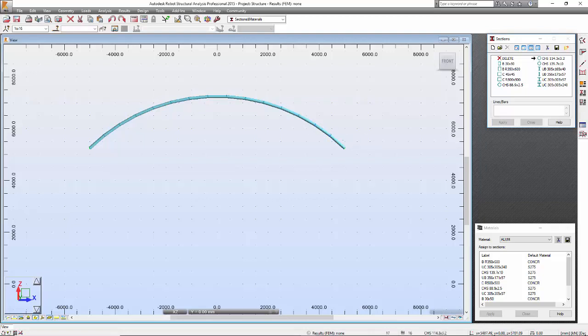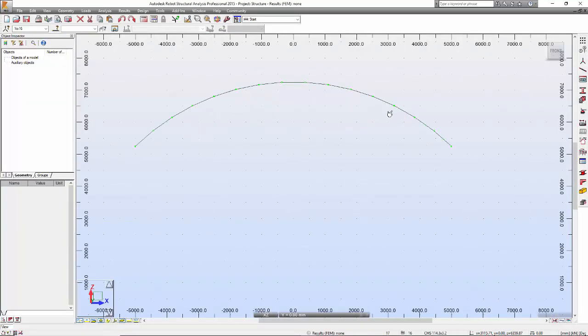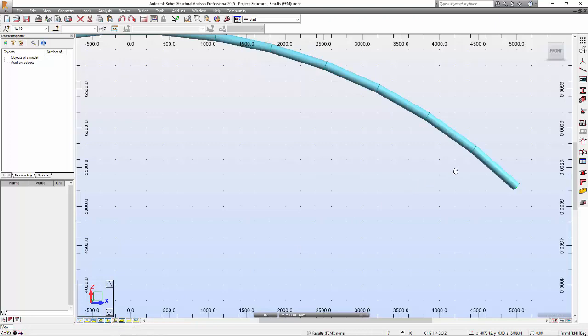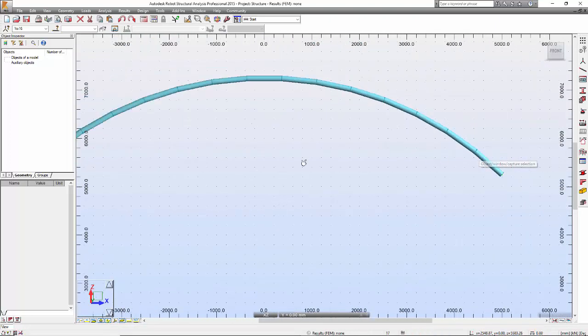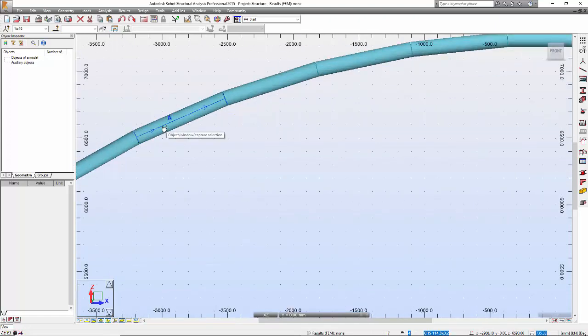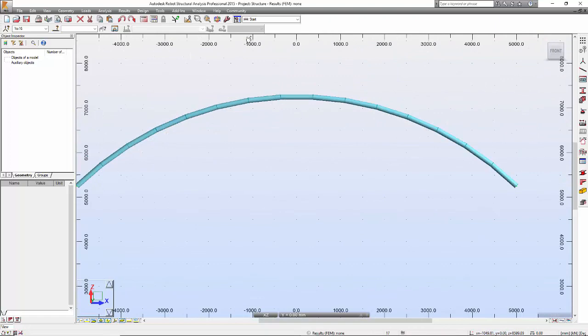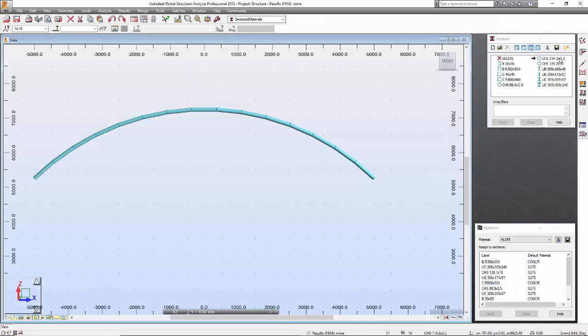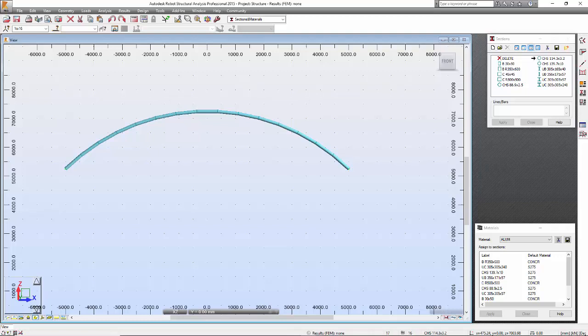If you want to have a look at the detail, you can come back to the start, and then you can switch on the section shapes by clicking on this one. So this is a cross section bar, okay? The size, I can't remember now, so let me check. It is 114.3 diameter, and then thickness 3.2.